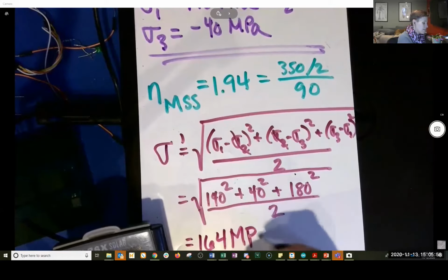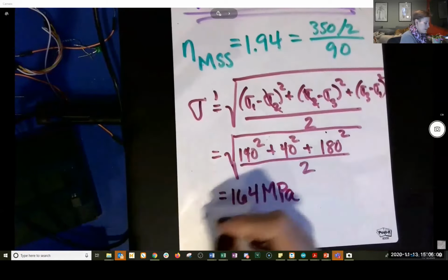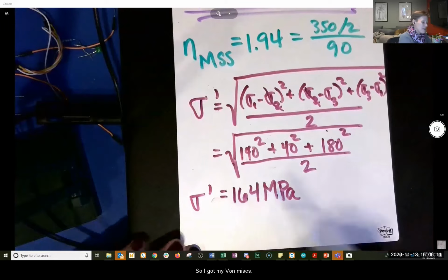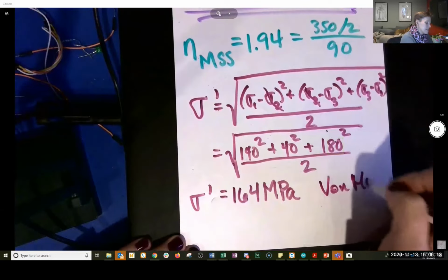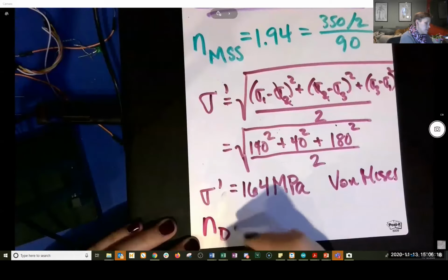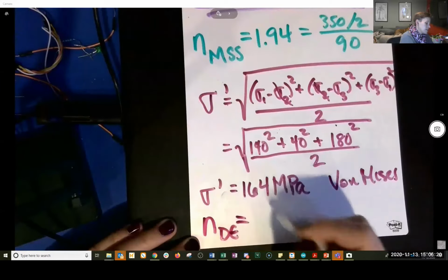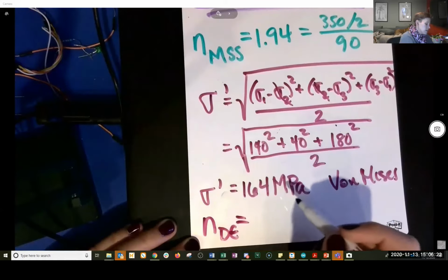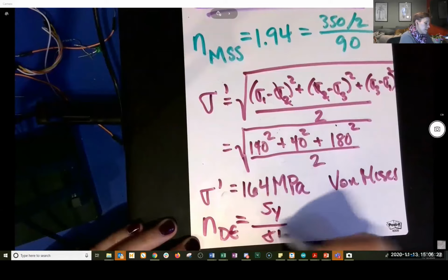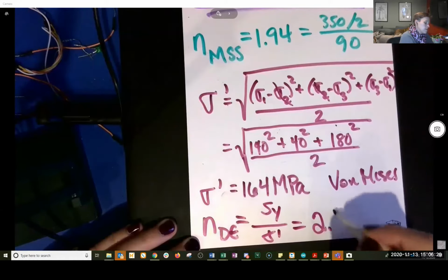So I'm going to stop here. That was all kind of subtracted in my head, so that could be wrong by a little bit. Okay. I didn't, it's already gone. So can you say it again? 2.14. Yeah, it sounds right. Okay. So I have my von Mises stress. So this is my von Mises stress, the good predictor of failure. So my distortion energy factor of safety. Whew. Okay, yield strength over von Mises, and that is 2.14.